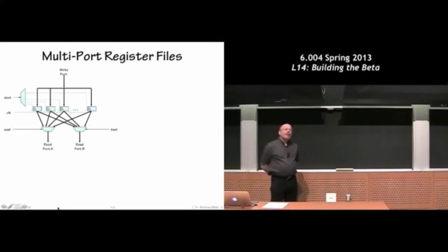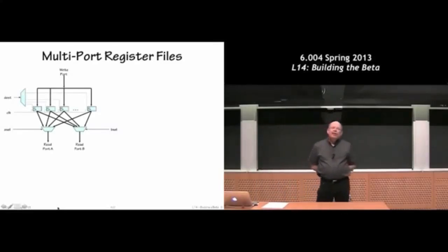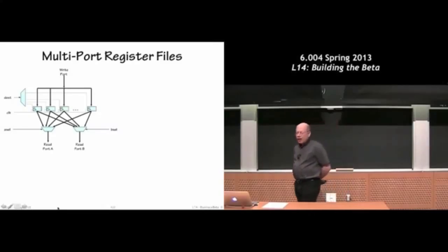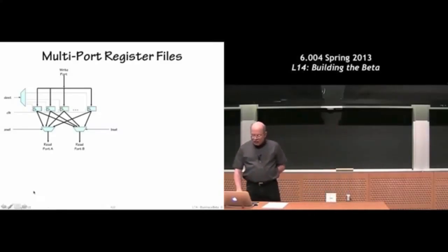Okay, so the first memory that we're going to deal with is our magic little array of these 32 scratch pad registers. They're placed where almost all the instructions get their operands and write their results. So we actually have this little group of 32 registers. Each one of these little rectangular boxes is a 32-bit register, can hold 32 bits of information. So these heavy lines here are actually 32 signal wires all coming in, in this case, to this particular register.